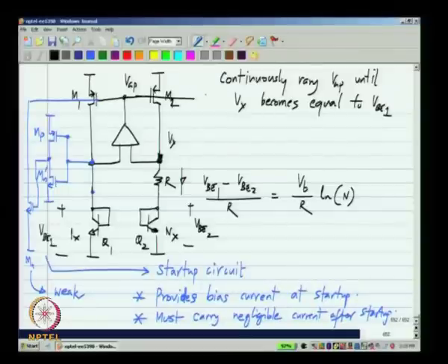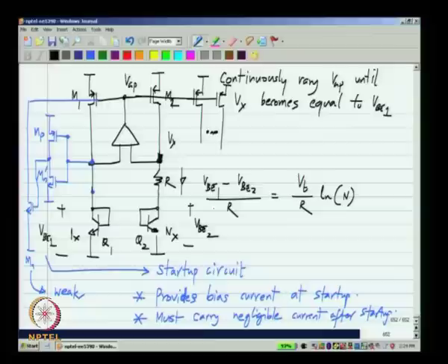So, we can replicate these currents any number of times we want. And I have used both bipolar and MOS transistors here. Our dominant technology is MOS, but if necessary, these current sources can also be realized using only bipolar transistors. And this op amp also is realized using either CMOS or bipolar, depending on the process that you have.